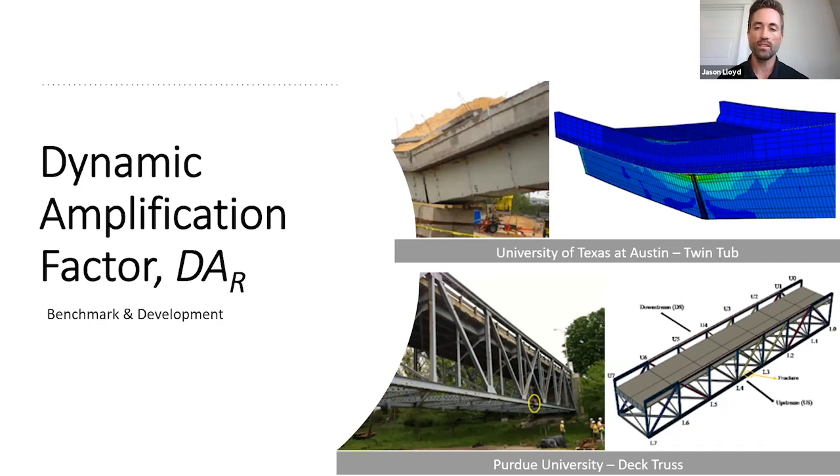Now, it's not usually practical to perform a dynamic system analysis to identify fracture critical members. So the researchers wanted to determine a simplified dynamic amplification factor that is multiplied by the static response of the bridge in the faulted condition, therefore accounting for these inertial effects. This amplification factor is applied to the load combination characterizing the dynamic failure event, which I'll get to in just a second. It's called redundancy 1.